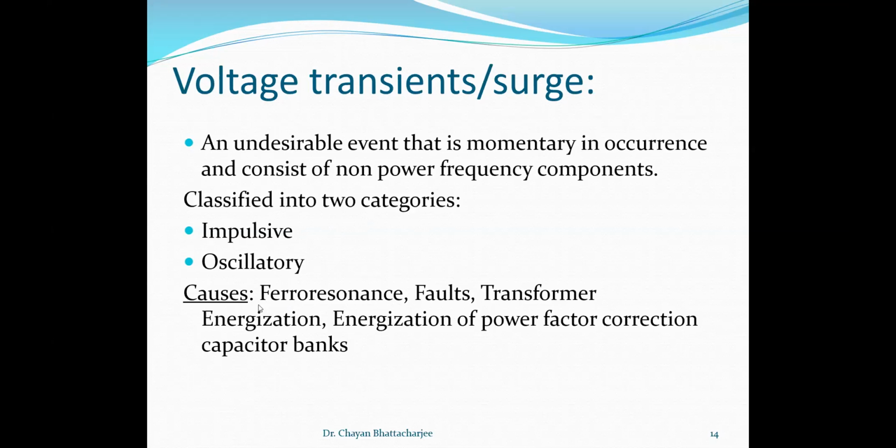What we have not discussed is ferro resonance. What is ferro resonance? It is basically a non-linear resonance observed in three-phase transformers. In some cases, the three-phase transformers are lightly loaded or not loaded at all, and they are supplied by large underground (UG) cables, which have a high capacitance.